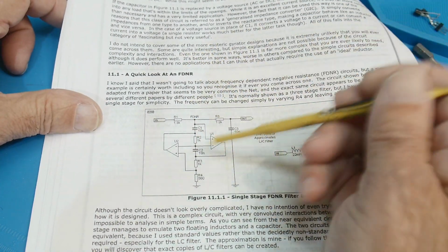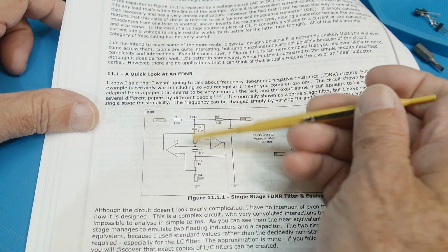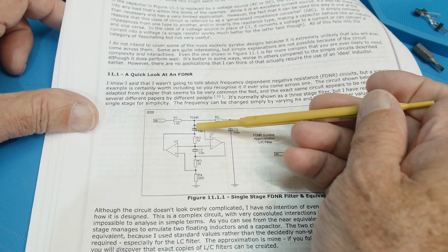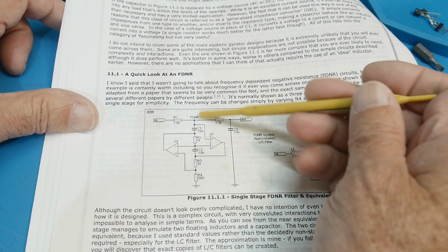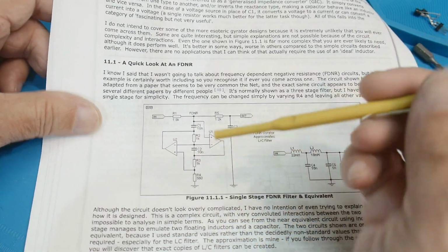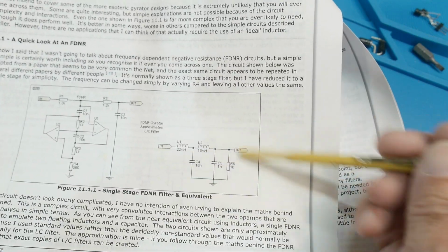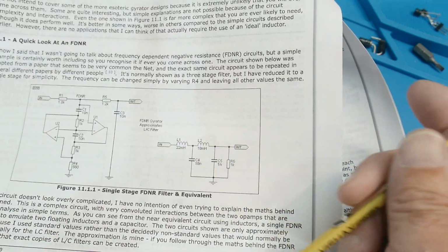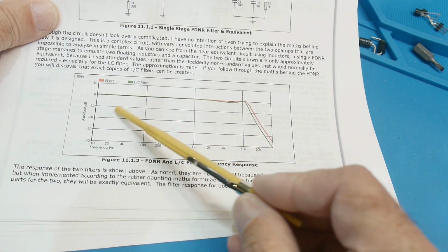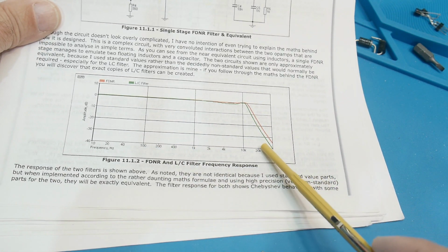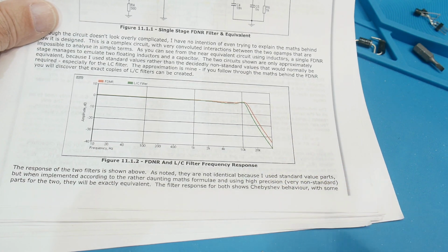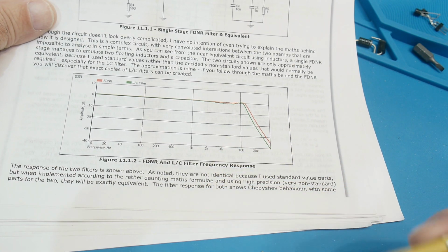And they have replaced 2 of the resistors with capacitors, the 1 location and the 3 location. They've replaced them with capacitors, and it should give you an equivalent of this circuit, which is 2 inductors and 2 capacitors, and give you a low pass filter with a little bit of ringing here and then a very fast fall off. So, okay. So let's take a look, see if we can reproduce this one.